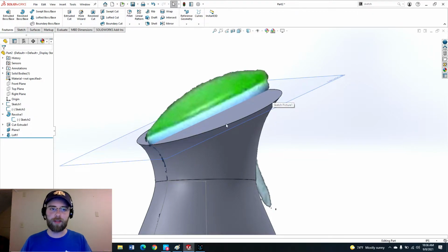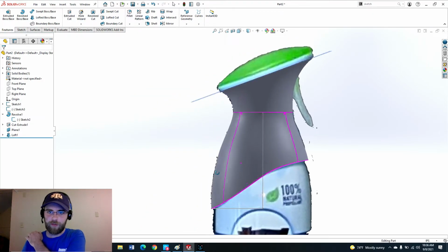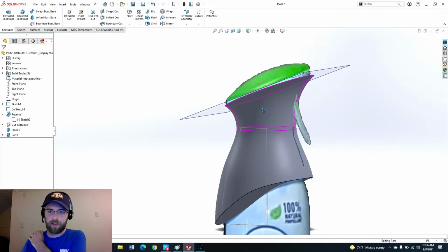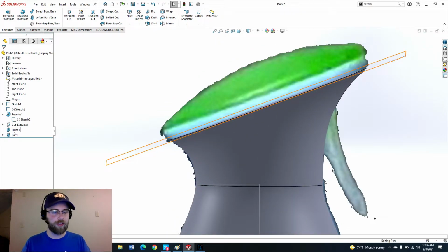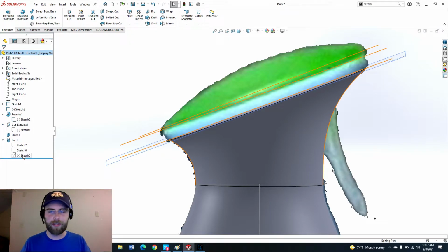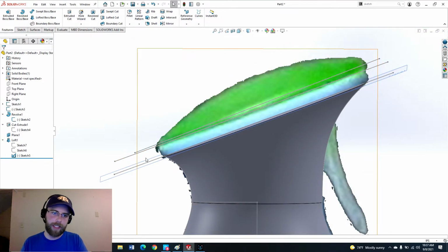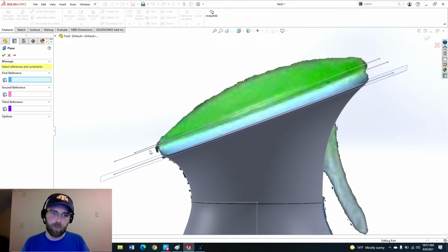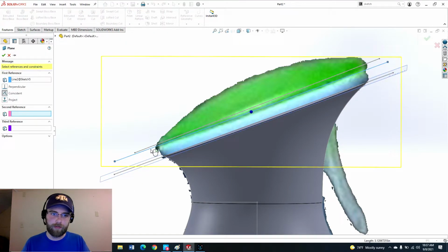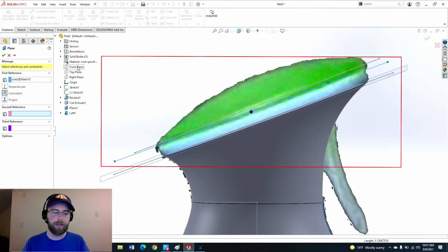And so the hard part of this is over. We've got the revolve and that cutaway. We've got the loft. So next we just need to figure out this top portion. So let's show our reference sketch again to get our other planes. So show, and we'll create a plane on both of these lines, just like we did before, where we'll pick that line, make it perpendicular to the front plane.